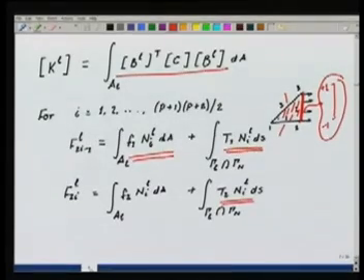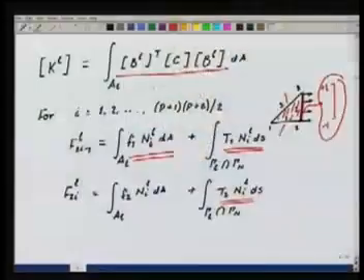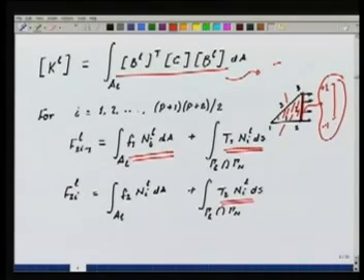Can't we do this in a more explicit way? This B transpose CB approach is commonly available in all the books, and this is what people follow. But something I don't like personally is that here we are dealing with matrices. We have to store these matrices for every integration point, because this integral will be written as a summation over integration points.